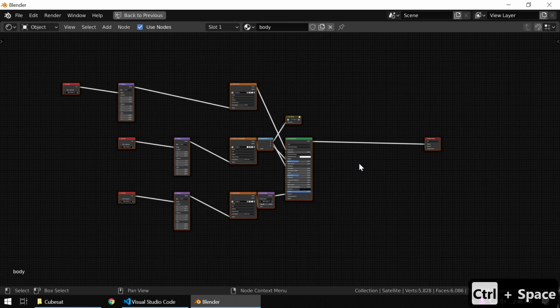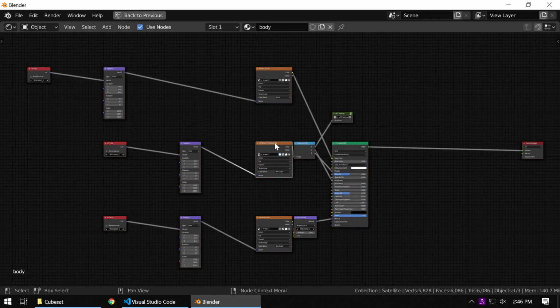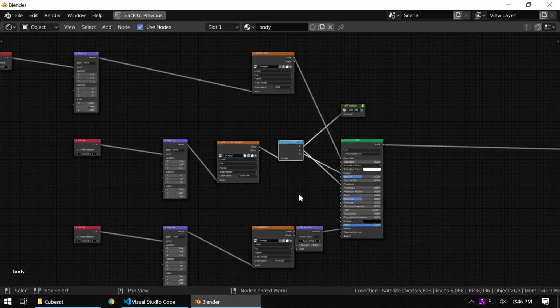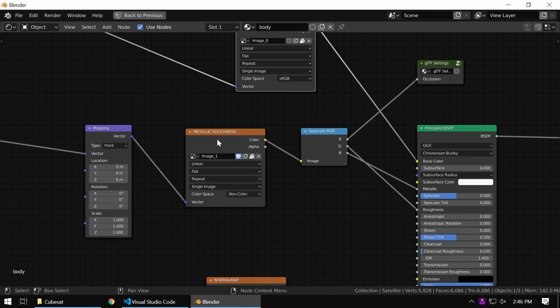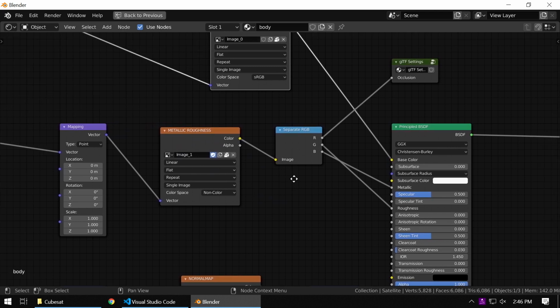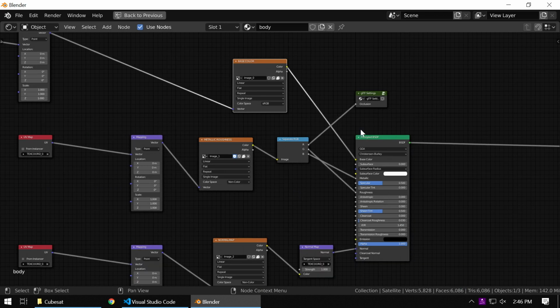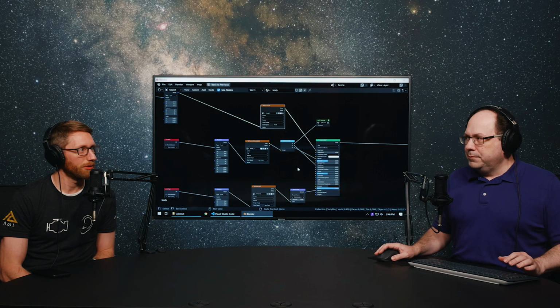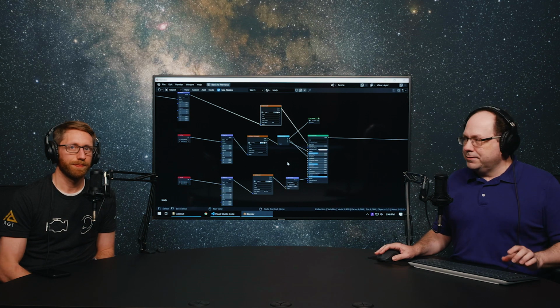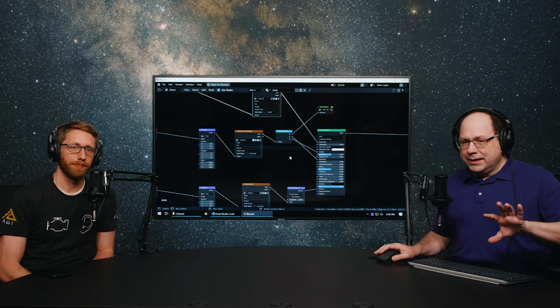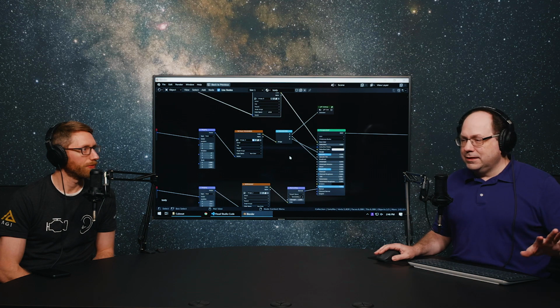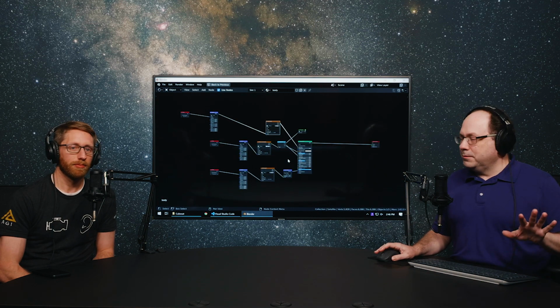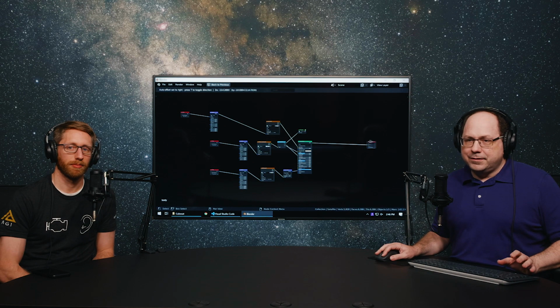The GLTF importer actually builds this graph when it imports a GLTF material, and it has a lot of different nodes and different images. Right, and in GLTF, materials don't use this shader node graph building, so it extrapolates it based on the definition that's in the GLTF model. GLTF has a well-defined PBR material model, but it does not use shader nodes like this. So the Blender GLTF importer has actually constructed these nodes to try to teach Blender what was in the file so that Blender can render the same thing.